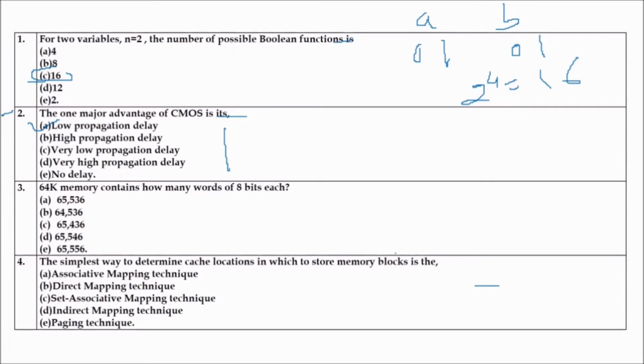The characteristic parameters for the CMOS gate depend on the power supply voltage, VDD, that is used. The power dissipation increases with the increase in voltage supply, and the propagation delay decreases with the increase in voltage supply, and the noise margin is estimated to be about 40% of the voltage supply value. So that is around 40%.